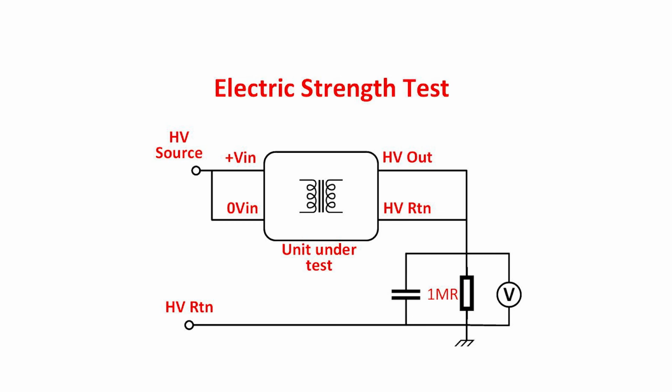Connect a high voltage source and slowly wind up the voltage from 0 to the isolation rating of the product, never above. Check your measuring instrument and then wind the voltage down just as slowly. And finally, ensure that everything is fully discharged before it is touched.